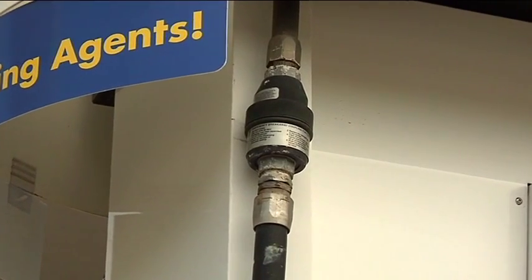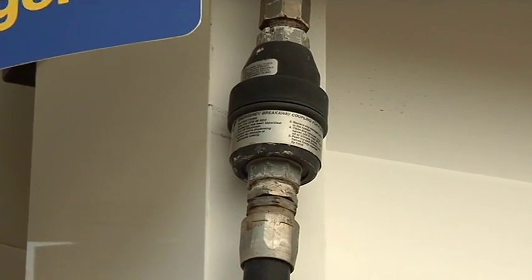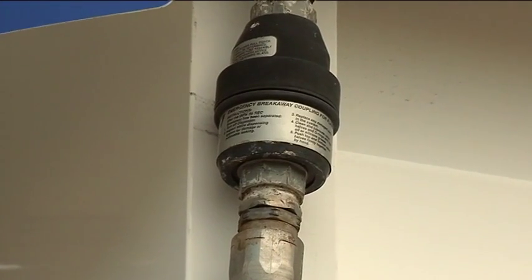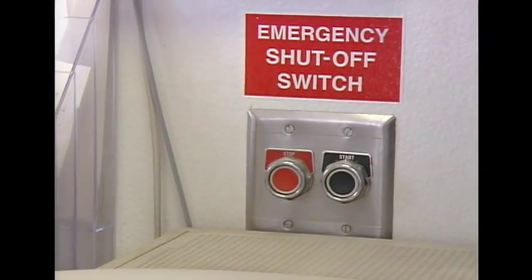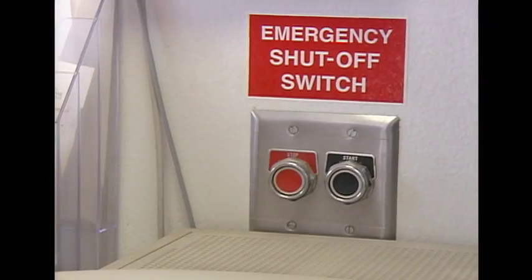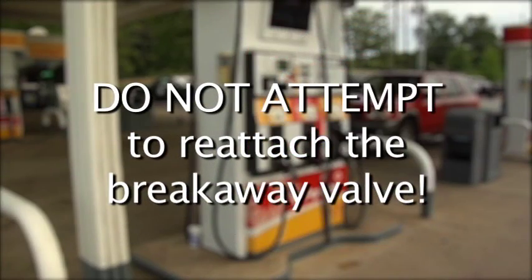Dispenser hoses are equipped with emergency breakaway devices, which are designed to prevent a release of fuel if the hose should become separated, such as during a drive-off. If the breakaway becomes separated, immediately shut off the dispenser and check for any spills. Do not attempt to reattach the breakaway valve.